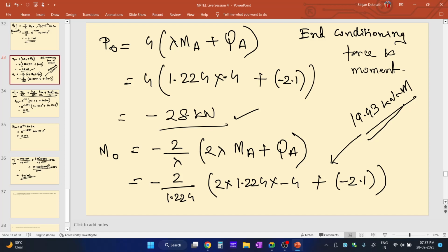In order to avoid the shear force, we are giving some moment and we are giving some counteracting force in order to counteract the moment and shear force that is coming from the original load that is acting. Okay, that is the P, that is 100 kilonewton. So we are just giving some counteracting moments, we are assuming, and after that we are mathematically calculating those in order to find out the deflection. Actually the derivation is like that.